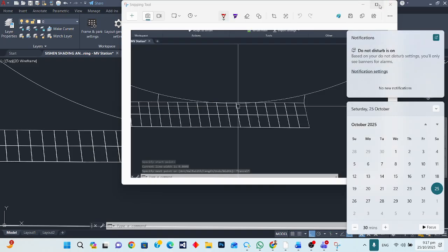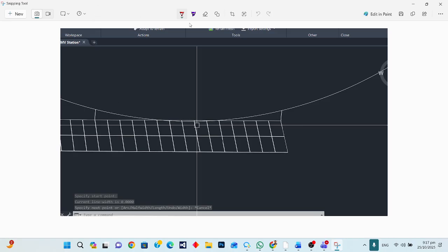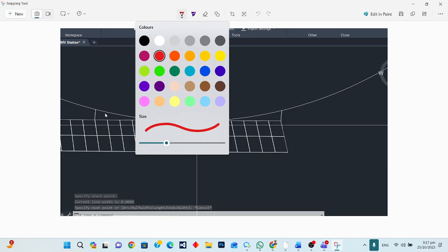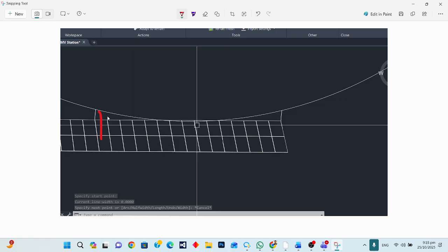I want to say that this is the area which is protected. But in that area, you can see that the rolling sphere is touching the PV module. So in that area, there might be chances that a strike hits the PV module and damages it. This area is okay.